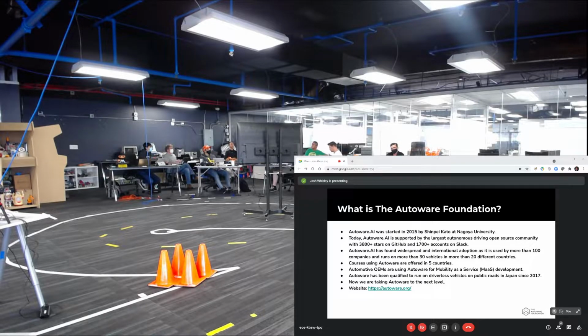They also have a fork of ROS2 that is already ISO 26262 certified. ISO 26262 is what's called safety element out of context. It means you can prove essentially that this stack of software is functionally safe. And so they have a fork of ROS2 that is certified as functionally safe. And it is API compatible with ROS2, so you can run ROS2 code on top of their hardware ports.